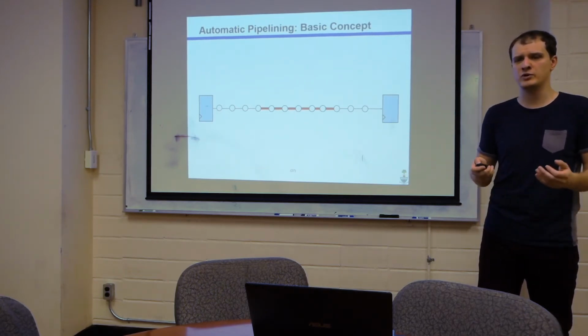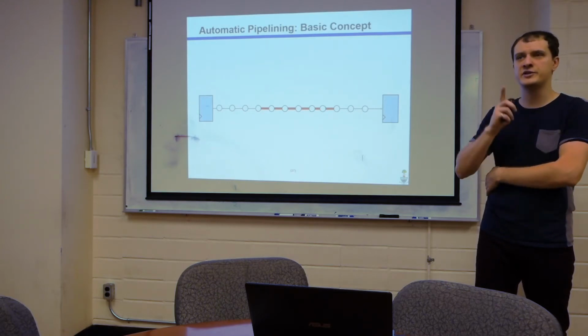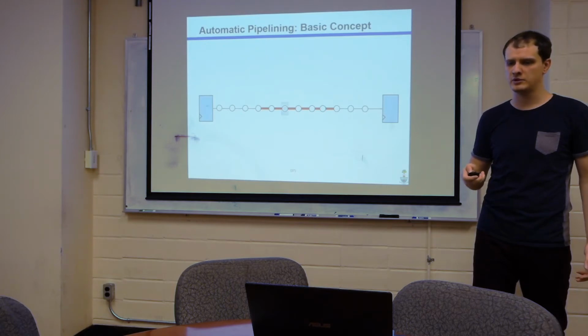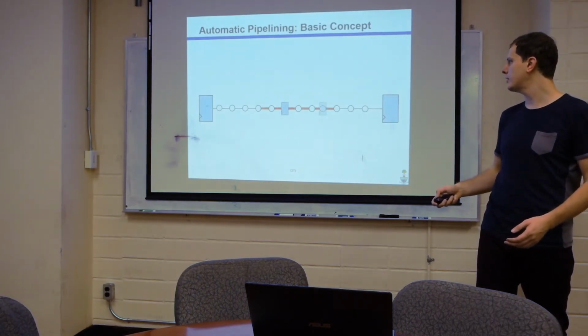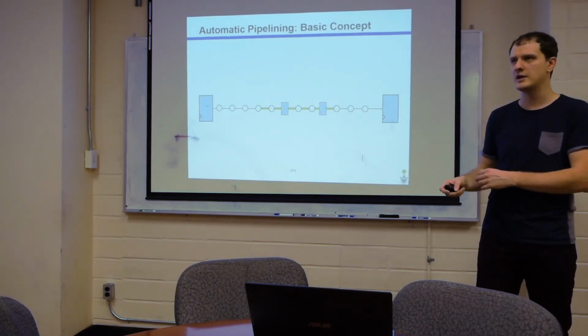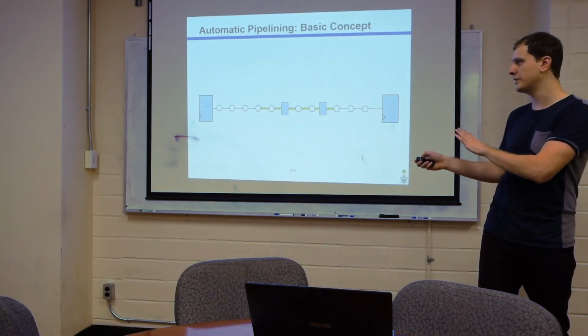We know for sure that we need at least 1 register to go in here, to pipeline it. We don't know if it's just 1 register. It could be 2, it could be 3, but we know it's not 0. So maybe that's not enough. Oh, this happens to be enough. Okay, great. Now it's split into 3 segments that are all underneath the logic depth. Okay, this is the beginning of how I'm going to approach it, but this isn't currently helpful.